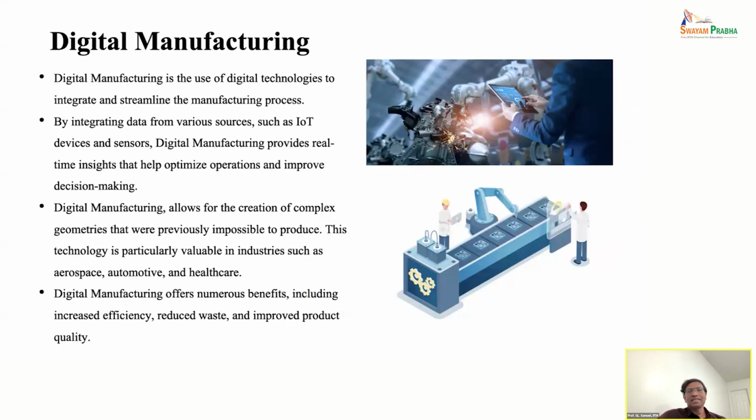Now, one requirement to apply artificial intelligence principles to manufacturing is that first we need to make it digital manufacturing. As long as you have a lathe machine which is very mechanical, with no sensors, no CNC or anything, you can't make it automated. There was hard automation, but that is mechanical hardware where you set limit switches and put a reverse so that something moving forward can go back and then move. That is called hard automation. But now what we are talking about is soft automation, where with computer programs we can control the machines and change the task they are making. So this is more flexible.